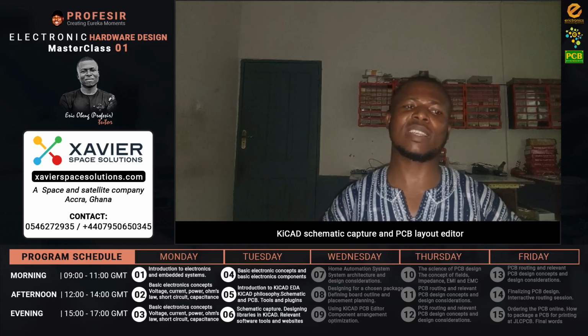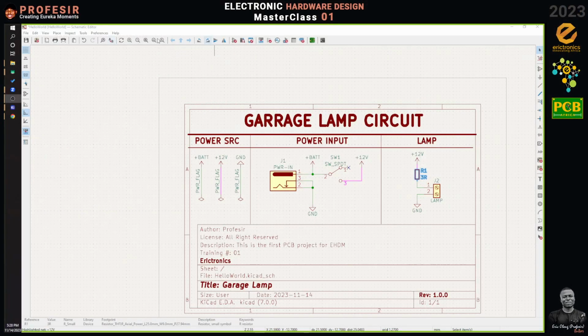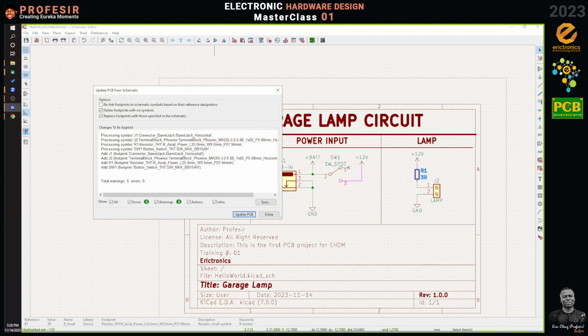Now let us export our work to the PCB. I said earlier that we can do that by going to Tools, Update PCB from Schematic, right? Once we do that, we'll get this dialog box showing us if there are any errors in what we are doing. In case there are any errors, let's say some pin mismatch or some pins not connected, we will see that, right?